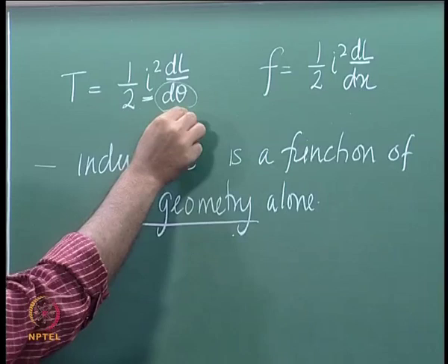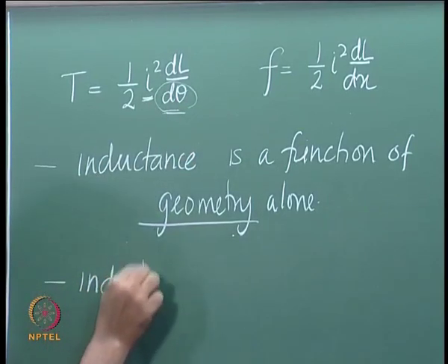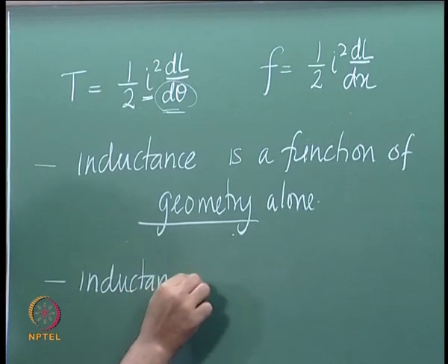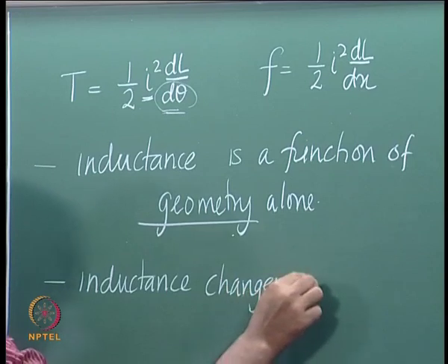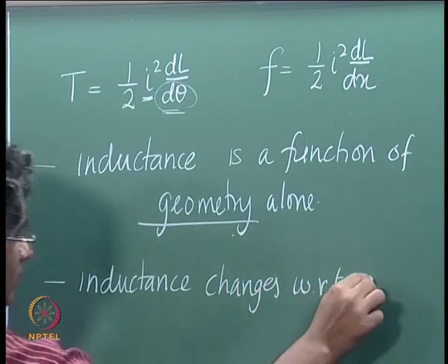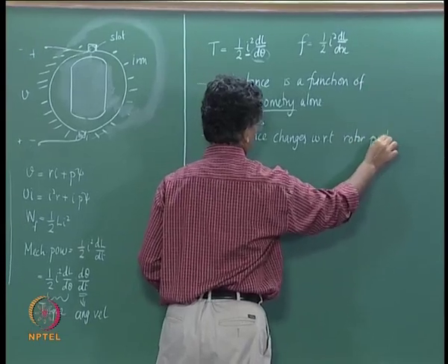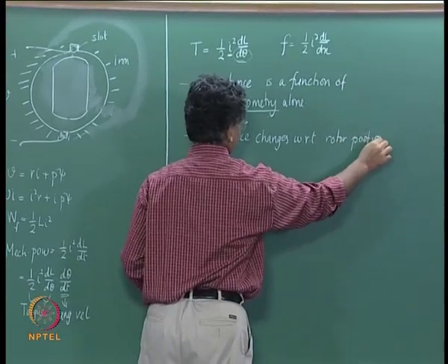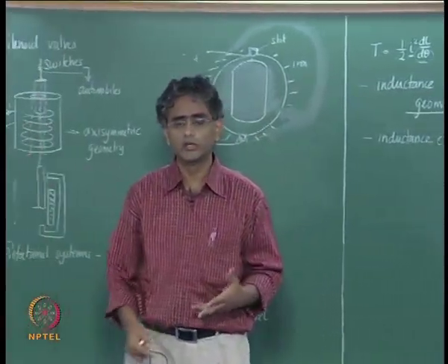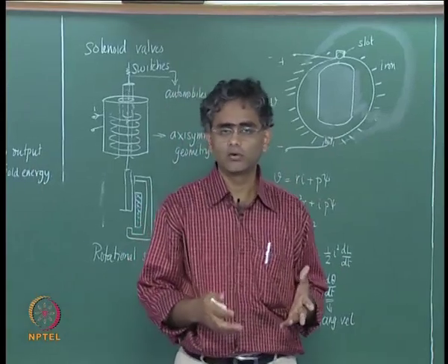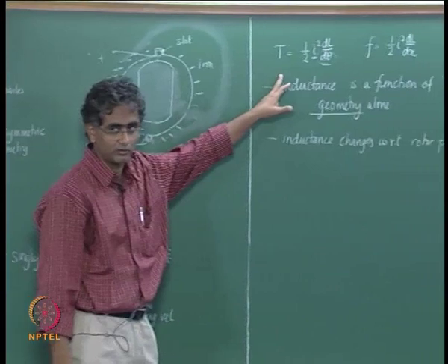It is therefore important that some inductance changes with respect to rotor position. If inductance does not change with respect to rotor position, then the machine will not rotate, you will not be able to develop a generated torque.